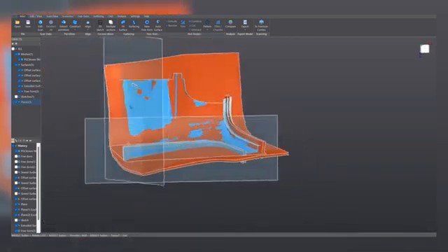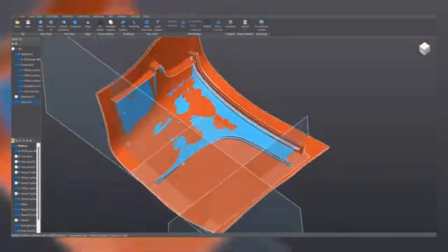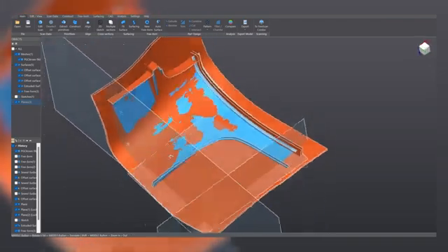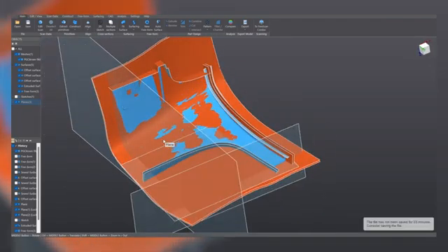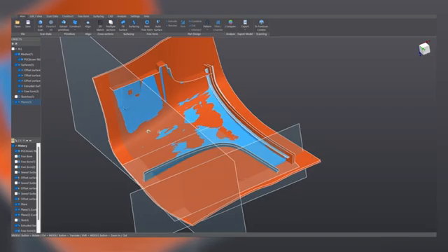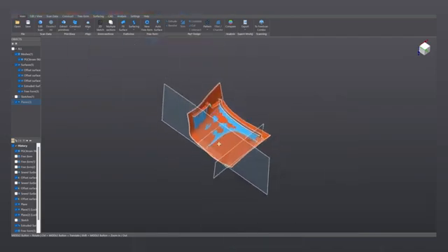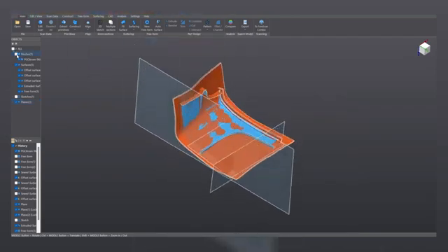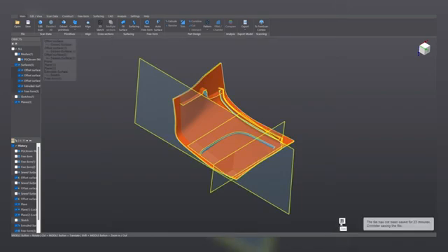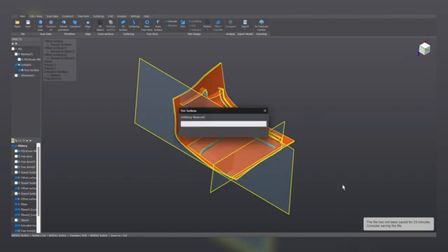And now we have all the surfaces and planes, all the features, to close the solid, and so obtain the shell of the mesh, which is going to result in a solid body. In order to obtain that, let's hide the mesh. Let's select all the surfaces, and we are going to click on this small button over here, which is trim. Now the software will need some time to compute all the intersections between all the surfaces, and we are going to continue later.